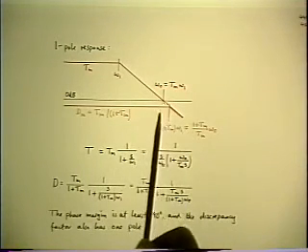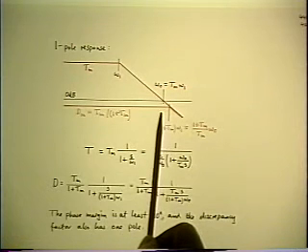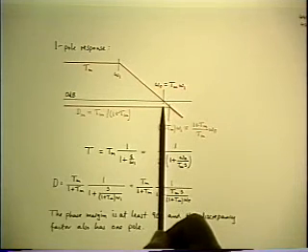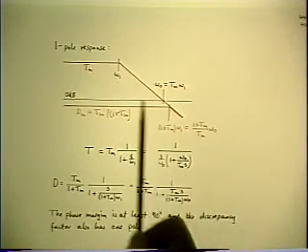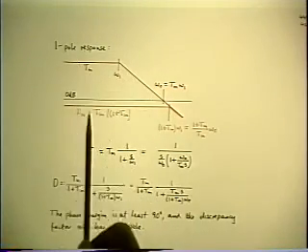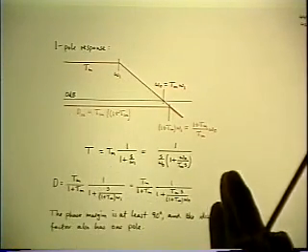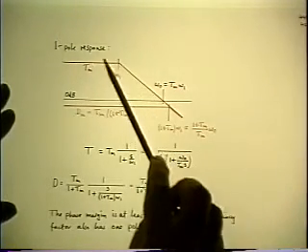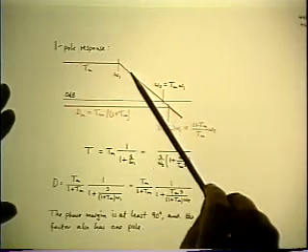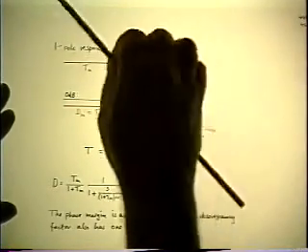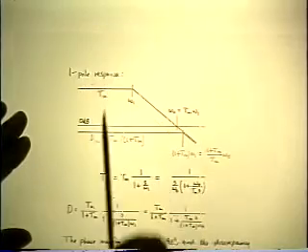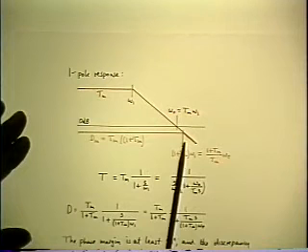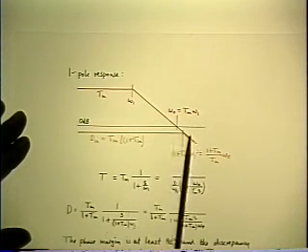Now, we're concerned only with the shape of D. And the only important part of that is near the crossover frequency of the loop gain, because as long as the loop gain is large at lower frequencies, the shape of D is going to be close to 0 dB, which is where we want it to be. In other words, suppose there were a much more complicated shape of T down here. Suppose there were some more corner frequencies. What would happen to D? It would get little wiggles in it. But we don't care about those.